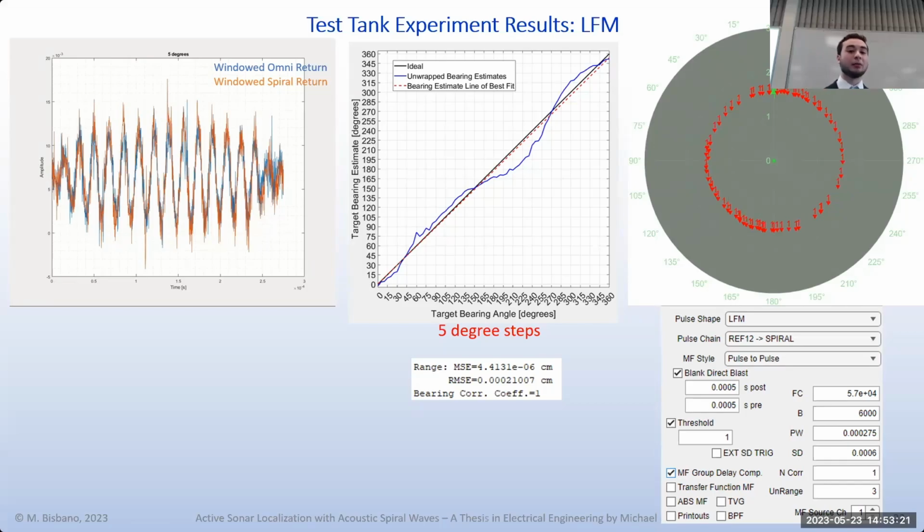What I first see is the slope is always positive on this. So I think you could fit a curve to this and then draw it to a linear curve. But beyond that, you could just have a calibration file of your transducer setup and how it's mounted, and then fit the curve to that, and then pull your points back to where they would map to on a linear 0 to 360 sweep.